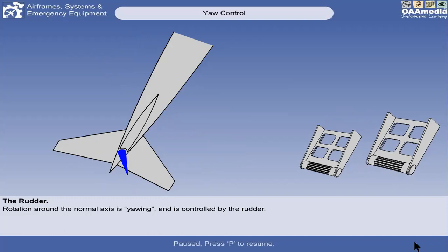Suppose the propeller is rotating counterclockwise, there is a tendency for that aircraft to yaw to the right. Okay? One way to compensate for that is by deflecting your rudder. Actually, it's not the whole rudder that is deflected, no?